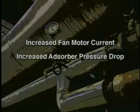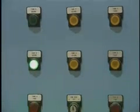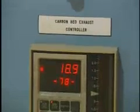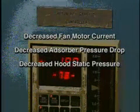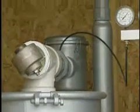Gas flow rates above the design range of the adsorber can potentially lead to breakthrough. An increase in the gas flow rate is indicated by increased fan motor current, increased adsorber pressure drop, and increased hood static pressure. Decreased gas flow will result in reduced capture of the contaminants at the source, resulting in fugitive emissions. A decrease in the gas flow rate is indicated by decreased fan motor current, decreased adsorber pressure drop, and decreased hood static pressure. The regeneration frequency and cycle time should be compared to the baseline values.